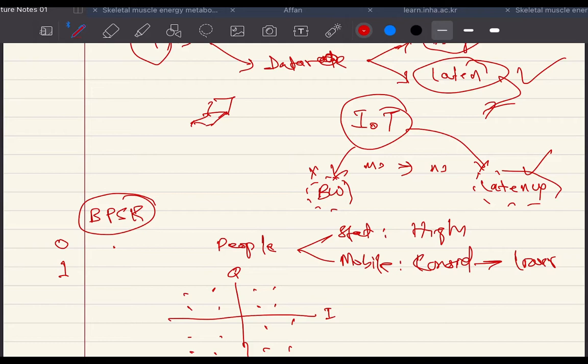So when you are transmitting 0, you are starting from minus cos something and you are using 2 cycles. But when you are transmitting 1, you are doing the opposite way. So it means that you are having only two states, this state and that state. So when you are sending 1, you are using this quadrant, and when you are sending 0, you are using that quadrant.